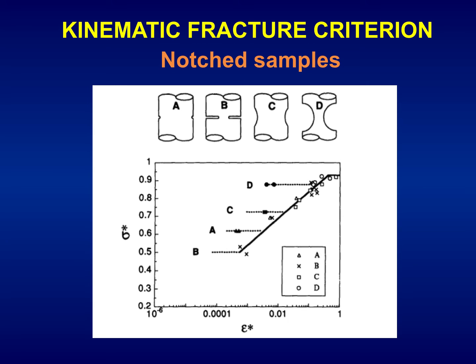The space average is computed over the extension of the tearing topography surface or hydrogen-assisted micro damage, critical distance concept, process zone or critical zone for failure in hydrogen. And in addition, we compute it as an average in time along the test duration from 0 to the critical time or hydrogen embrittlement time.